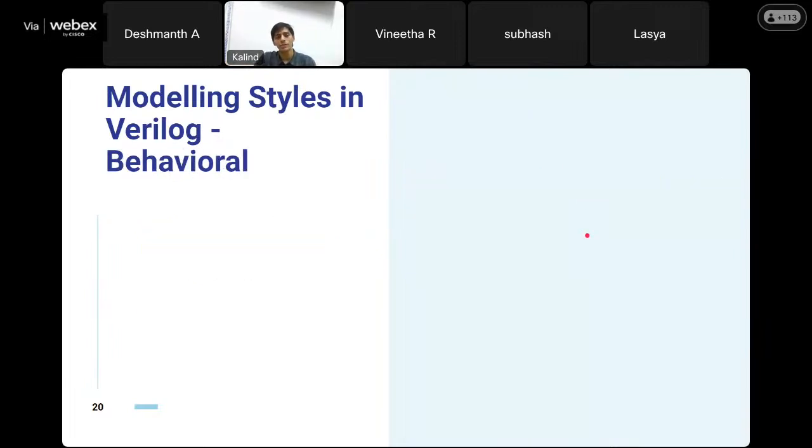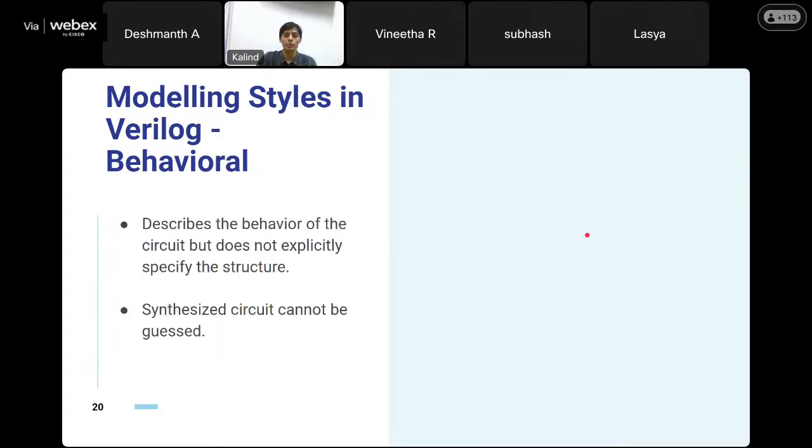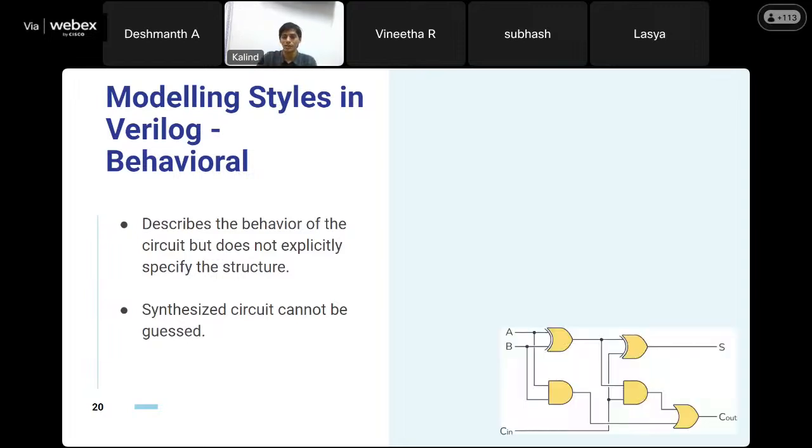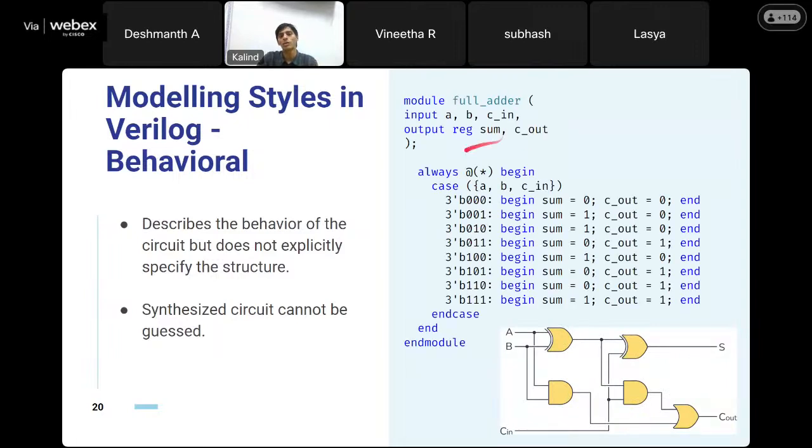Let's move on to the last one, which is behavioral. Now, as it goes by the name, in the case of behavioral, you are going to describe the entire behavior of the circuit without explicitly specifying the structure of the logic circuit. Again, if you are not specifying the structure, you cannot guess the synthesizable circuit. So again, same example, and this is what the behavioral modeling will look like in Verilog.